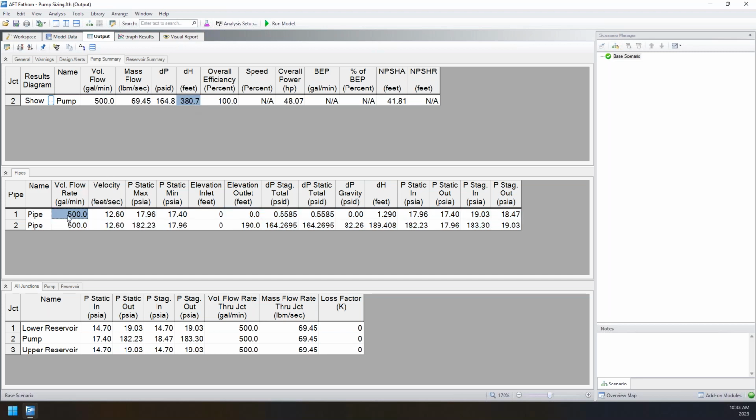There's a lot of other information provided in output, things like volumetric flow rate, which you can imagine as your system starts to branch, you'll get different results, not just a single linear system. Things like velocity, which we could check, are we exceeding our velocity limits? Maybe we're getting excessively high pressure losses or erosion in our piping. And again, a range of other parameters as well.